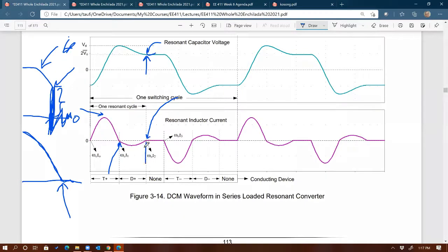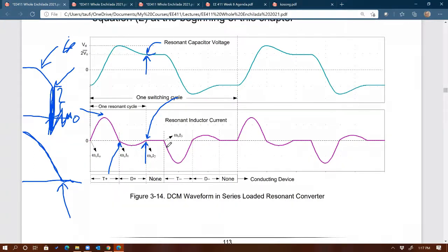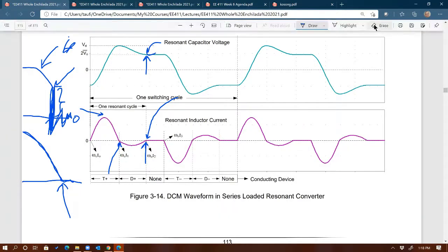Yeah, current basically soft switching. I don't know about soft switching, but basically we are not forcing the diode to turn off. Maybe that's what you meant by soft switching. So we are allowing the current to go to zero naturally, and then we turn off the diode at that point. So there is no reverse energy right there. That's why for this mode, it is okay to use a slow diode. You don't have to use Schottky's, which is an advantage.